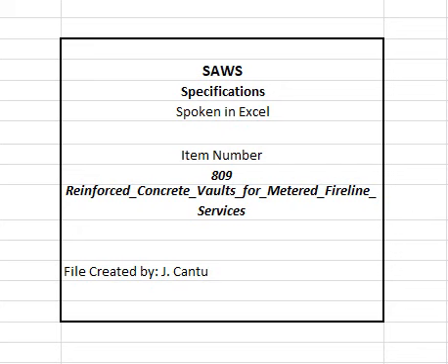3. Backfill. The contractor shall cover the openings at each end of the vault with grout placed around the pipe penetration inside and outside of the vault. A selected backfill, consisting of job excavated materials, finely divided and free from debris, organic material, and stones larger than 2 inches in greatest dimension, shall be placed in uniform layers not exceeding 8 inches in uncompacted thickness and shall be carefully compacted around the sides of the vault until level with the surrounding ground.